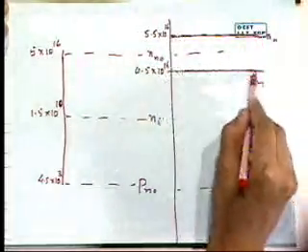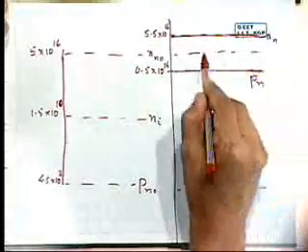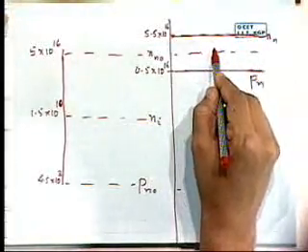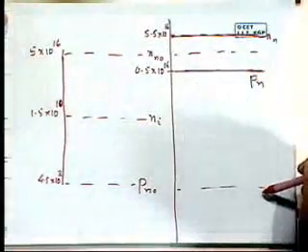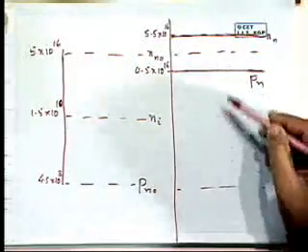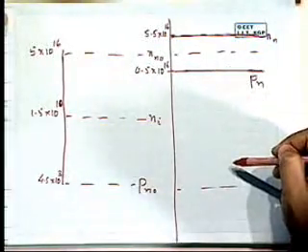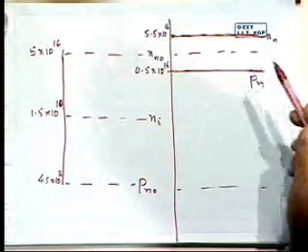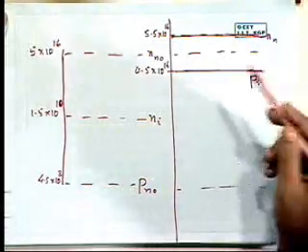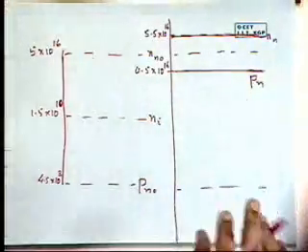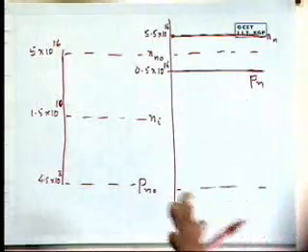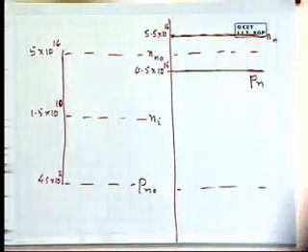So we've changed the electron concentration only marginally by illuminating in an n-type semiconductor, but the hole concentration has changed by about 10 orders of magnitude. Not 10, more than that, 15, 12 orders of magnitude. So that's what we had looked at last time. This is the effect of the illumination, which is to increase the hole concentration drastically.